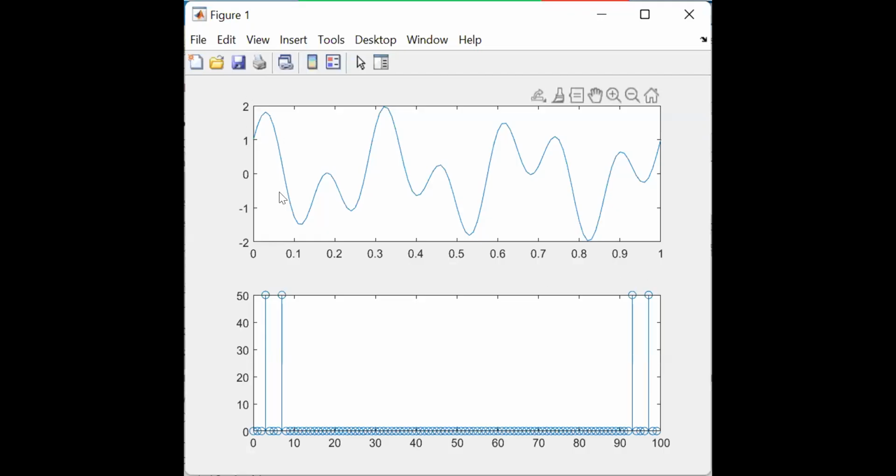Now you can see this spooky looking wave. It's actually a combination of a cos wave and a sine wave. You cannot make out anything from this particular diagram, right? But thank God there is the Fourier transform. I will click this particular thing. It shows a 3, indicating one frequency component of 3 hertz. And then there is one more. Let me click this here. Yes, this is a second frequency component of 7 hertz. So that is how a Fourier transform is useful. In the time domain, it looks like nonsense, but in the frequency domain, you can predict directly two frequencies.